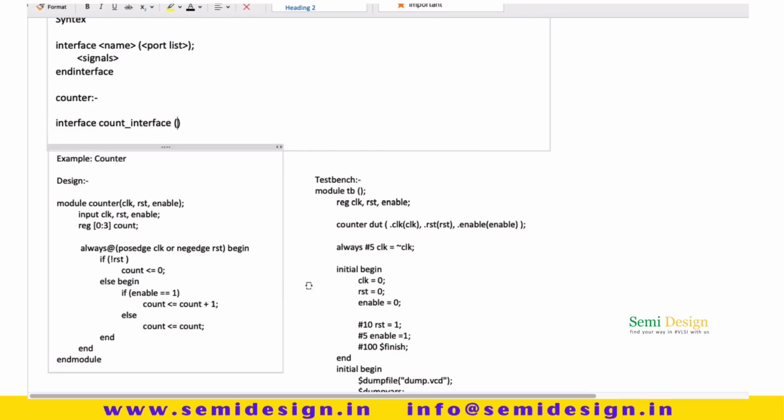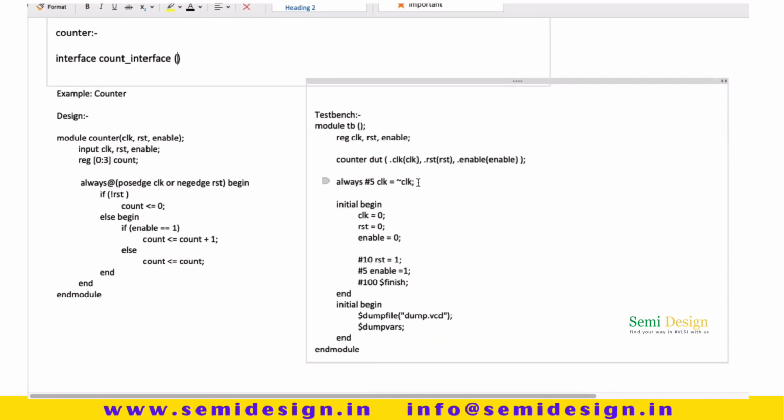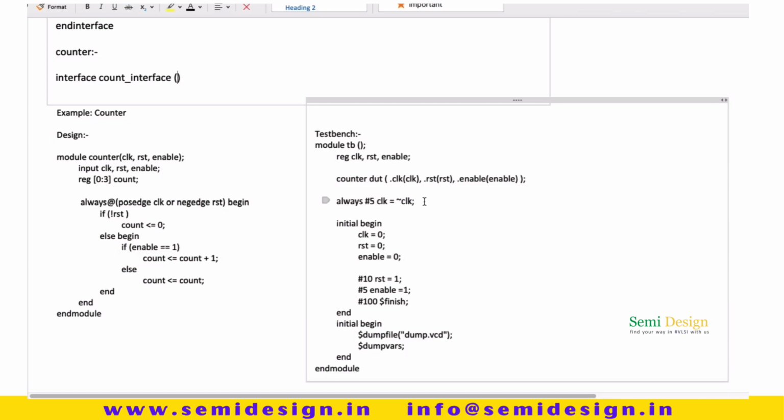Here we can see that in the test bench we declare the inputs clock, reset, and enable. We are giving the inputs to the design module and getting an output of count as an internal signal.